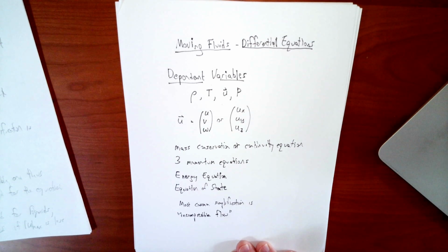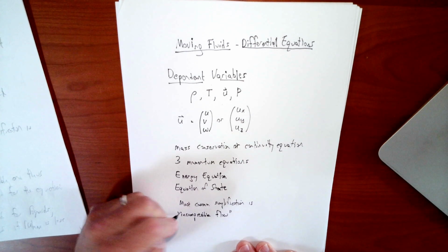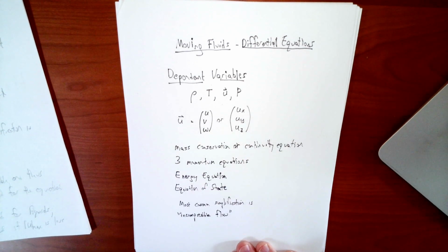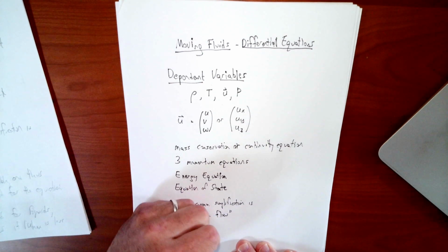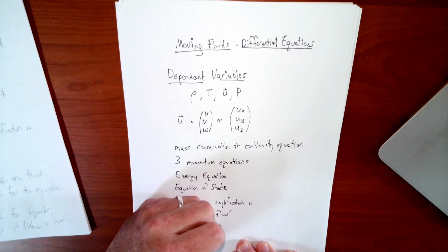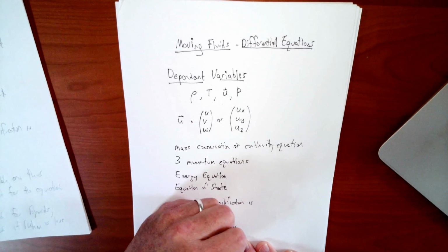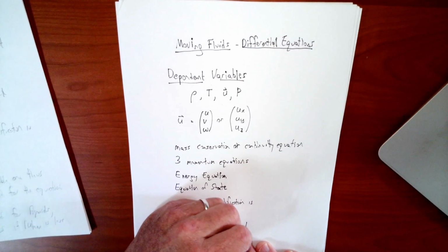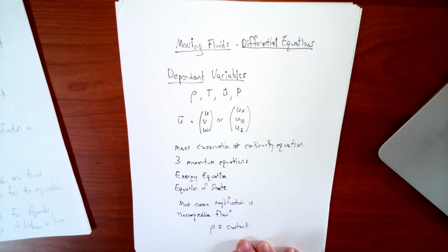There are plenty that aren't. I mean, if you want to study rocket propulsion, jet propulsion, those are compressible flow problems. The fluid is moving extremely fast, there are massive temperature changes. All of those things are going to cause changes in density that are quite significant. But for many, many problems in engineering and in life, you can treat rho as being approximately constant.